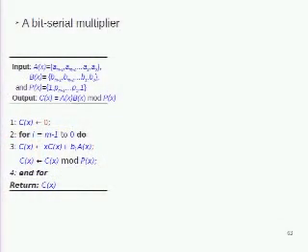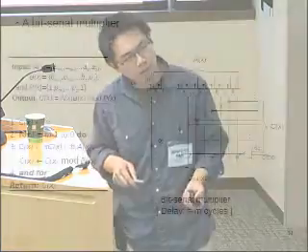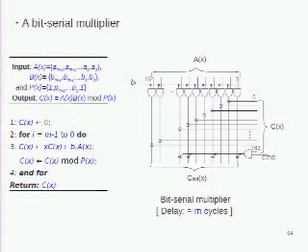If you look at the multiplier, this is a very simple multiplication algorithm. You want to multiply two elements represented in polynomial basis. You scan one bit by bit, and you accumulate, and you do a reduction. So this is the circuit that you use to perform one iteration of this. You have A of x here, it comes, and it's multiplied by 1 bit of B of x. So that's the multiplier.